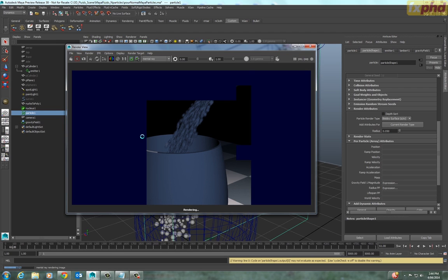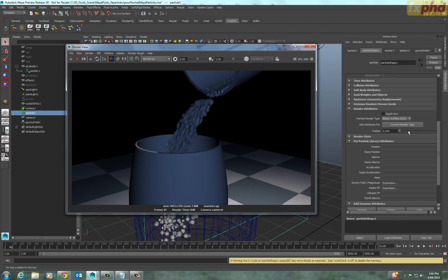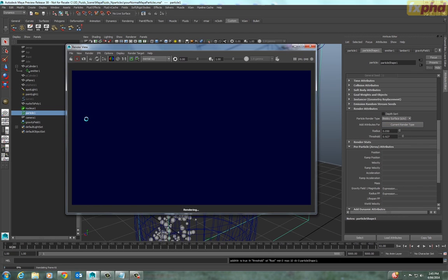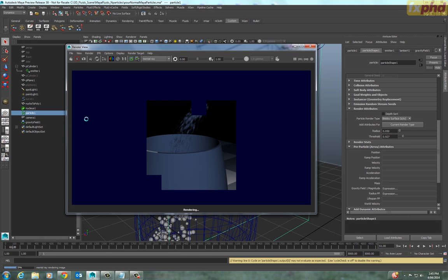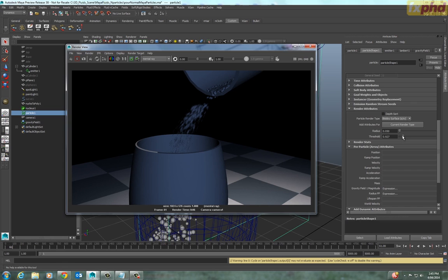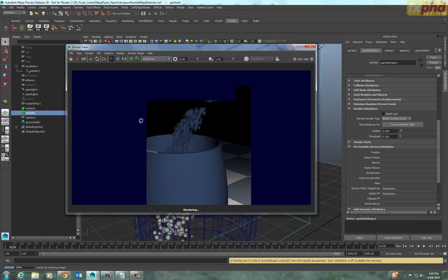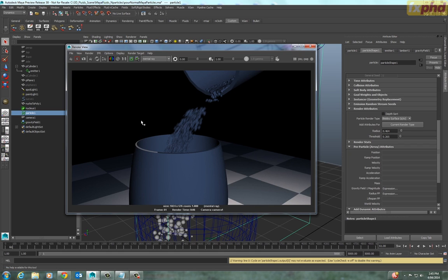So these aren't N particles; they're just the standard super fast Maya particles that you may or may not have used before. But there's nothing complicated about this setup. It's just an emitter, two colliding objects, and a random radius on the particle objects themselves. So I'm going to give it a go at doing blobbies, which blends spheres together into a kind of liquidy shape.